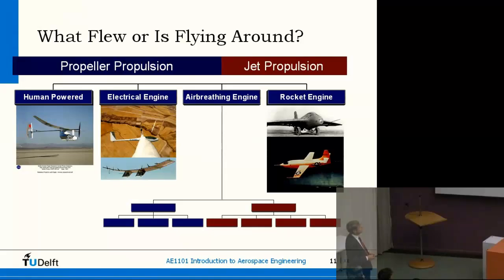Electrical engines, of course, are around. There are already small aircraft which have electrical propulsion. The question is, can it also replace high-speed, long-range propulsion? Here we see, for instance, one that's also solar-powered. In general, the amount of solar energy that the wing area catches is not enough to generate thrust for the airplane, even if you would have 100% effective solar panels. But maybe now I'm making the same mistake as the gas turbine committee by saying that that's not possible. Because the Solar Impulse, of course, is already doing something similar, but it's also halfway a glider.